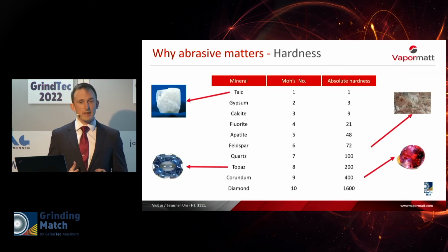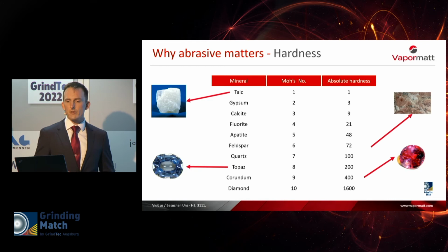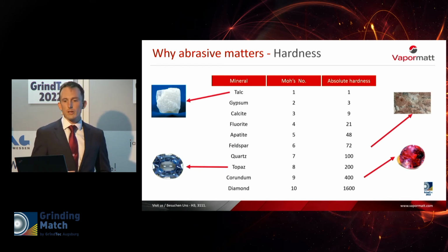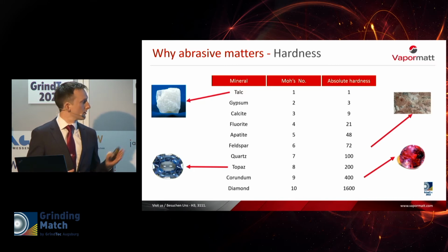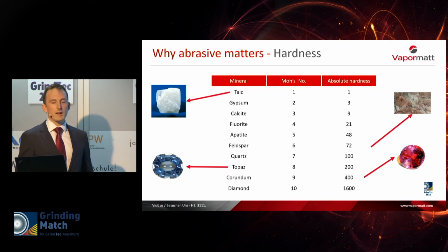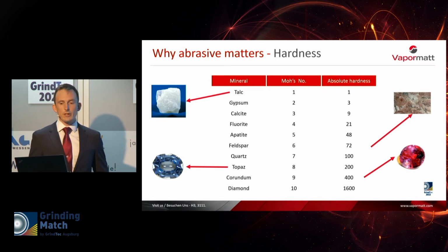After size, we can also think about hardness when specifying abrasive. It's less of a common consideration in carbide tooling because most users are going to be using a corundum or aluminium oxide. Aluminium oxide is both technically and commercially attractive because it gives a really nice balance in terms of cost and durability for the process. Where hardness can be a consideration is when users are looking to increase the intensity of the process or better understand how it will behave and break down while being used within a blasting process.